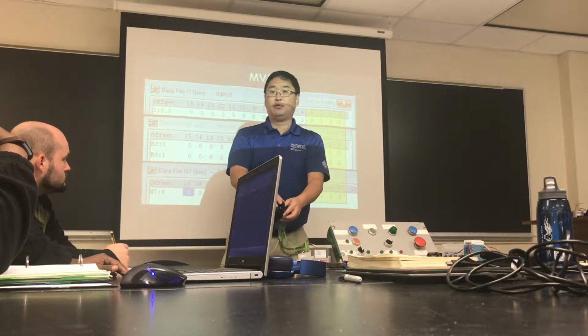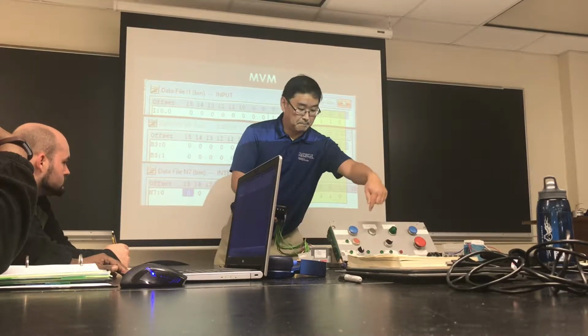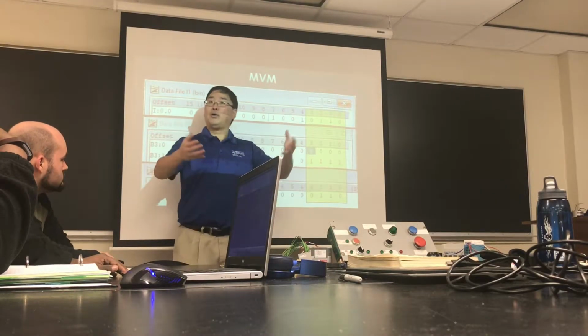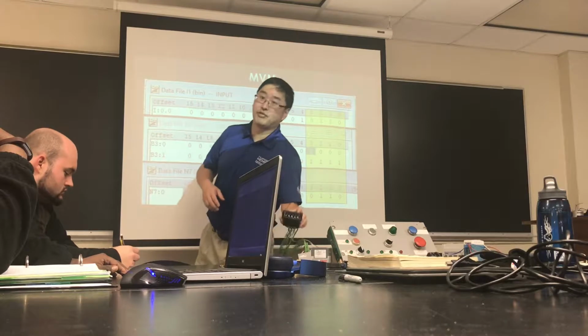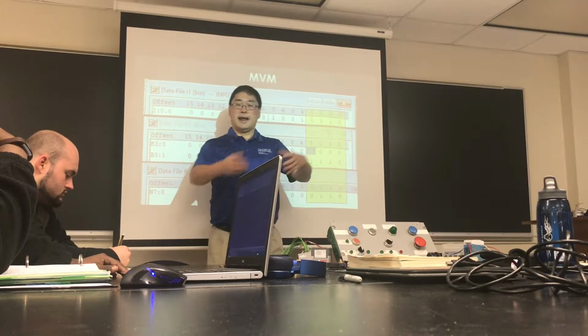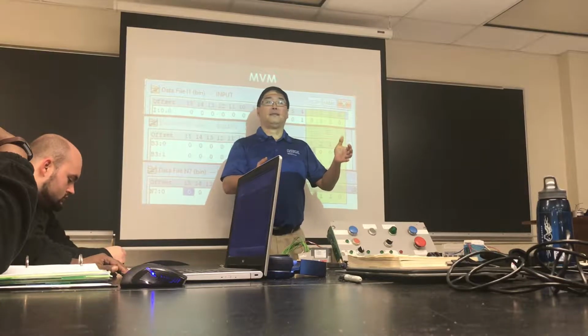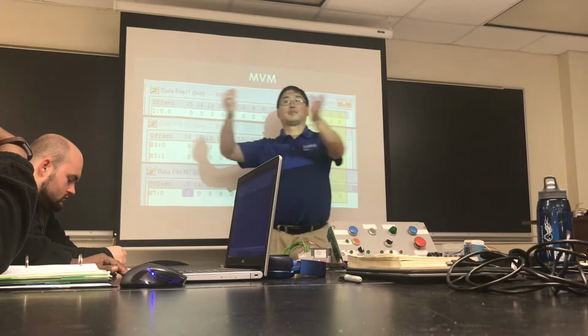So I dial in 12 and probably hit a button, and the system goes and gets the number off the thumb wheel and enters it into the PLC so I can decide, I'm doing part number 12 versus part number 8.